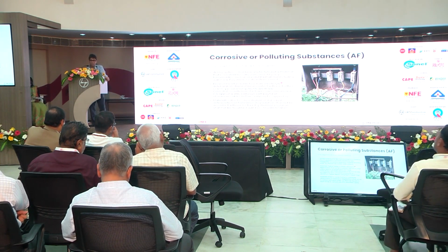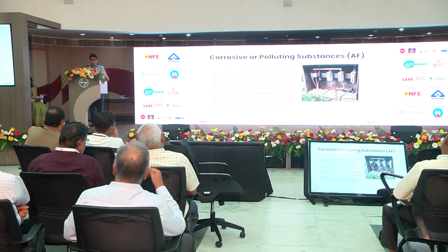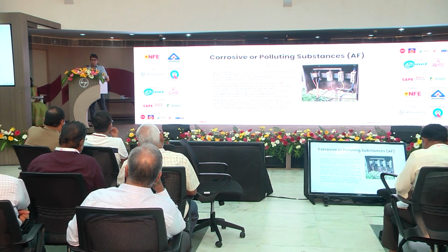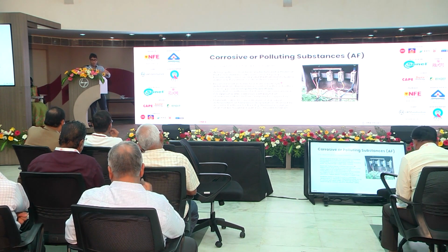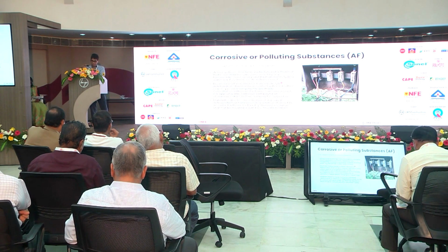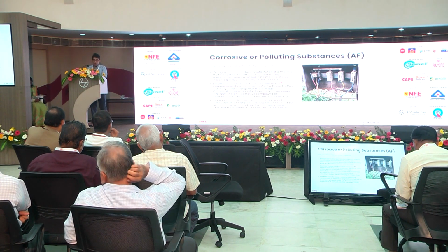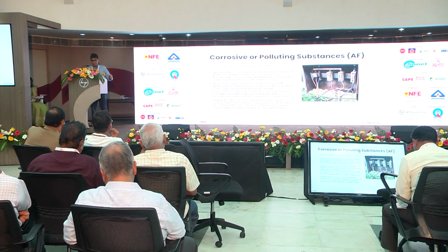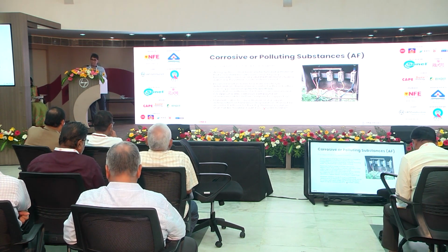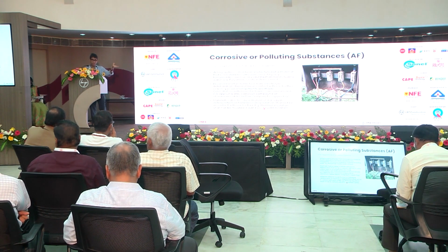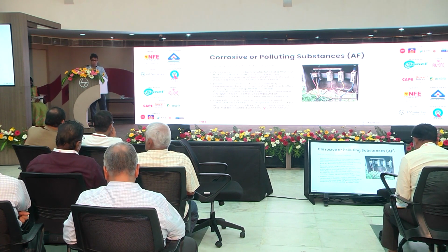Another interesting thing is we're starting to see a lot of modular homes and construction in India where you've got thermal insulation. They don't use brick walls. They use an aluminum partition. Then to create sound insulation, or in case of colder areas, even heat, you have thermal insulation inside. Very often, this thermal insulation, when it comes into contact with PVC insulation, will cause a degradation in the PVC insulation. Then your insulation resistance goes down, and as you know, that's cause for concern.